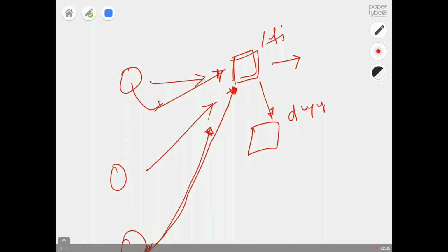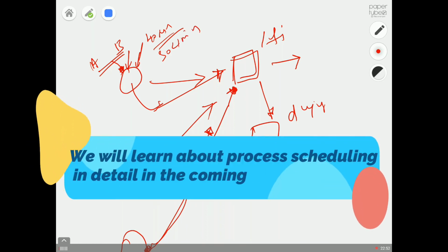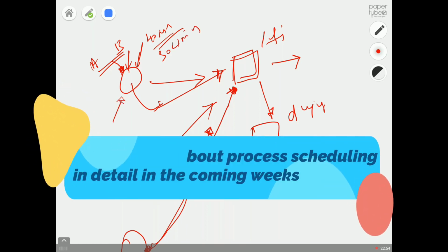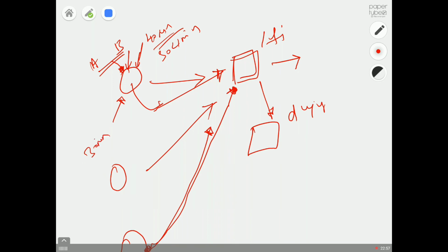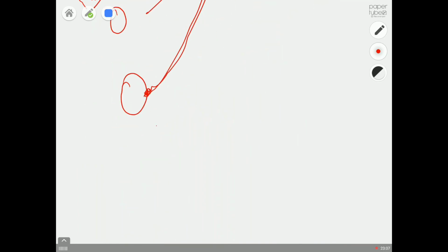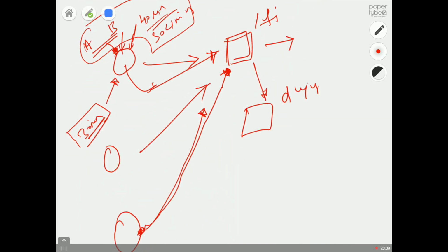It's not only the reaction time, but also the time you take to charge your reactants. In this case you are charging A and B, it will take some time. You are charging your solvent, it will take some 40 minutes if you set a flow rate of 30 liters per minute, and so on. And then after this we have a cleaning time, say 30 minutes. There are a few other things involved, so we should know the time involved in almost every operation that we perform with each of these unit operations. Only then can we come to this stage of process scheduling.